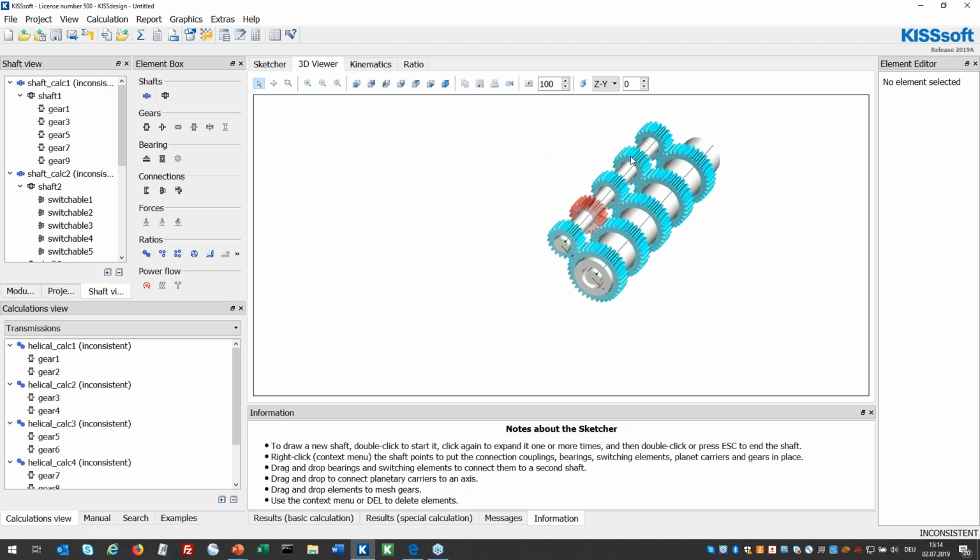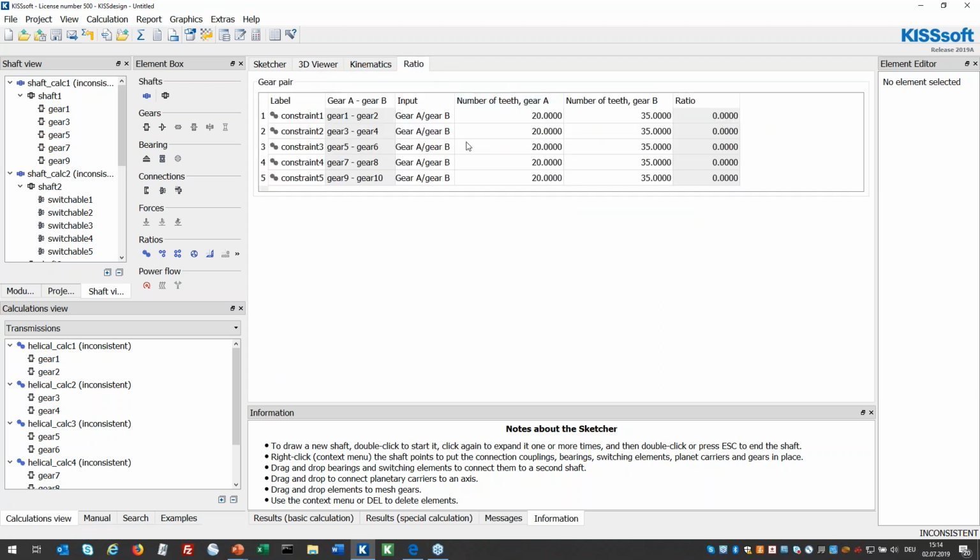They all have the same ratio, the same gears, but let's change that now. Now we want to have different ratios, of course. So I will just enter here some numbers for different gears, and I do it quite easy, quite logic, with the system of having the same sum of numbers of teeth, so that the center distance will be the same for all of them, as you will need to have also for shifted transmissions.